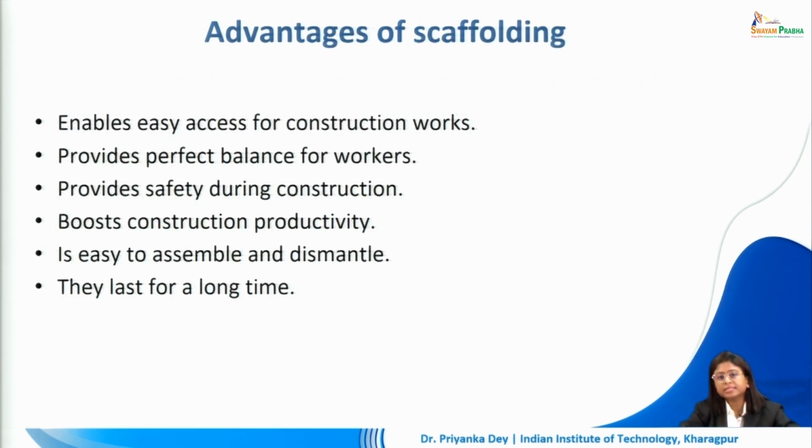First of all, it enables us easy access for construction work. We do not need to strain our hands to try to reach the upper levels, and we do not have to be on an unsafe ladder. So it provides a perfect balance for the workers and provides safety during construction. Most scaffoldings are designed in such a way that not only does it provide a working platform for the workers, it also keeps them safe from falling down and also protects other tools and equipment that is used at a higher level from falling down. So there are proper railings which are provided, toe guards which are provided, which prevent these materials from rolling off the platform. So they provide a very safe and balanced platform on which the construction work can be done.